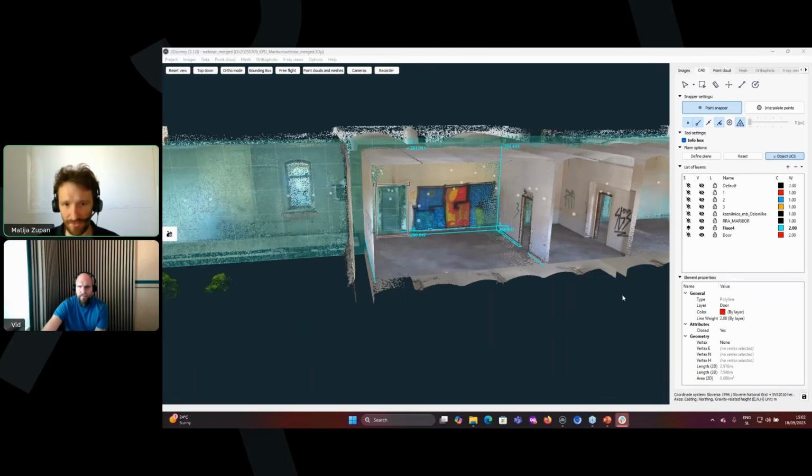So next question is, during the registration between MLS and UAV, have you only used GNSS RTK or have you used any other iterative algorithm? In this one, no, we did not need to, but we did try to use the iterative closest point georeferencing algorithms on other projects we did, in order to say this is the fixed point cloud and move the second point cloud and make it best fit the first one. We did try that before between different SLAM scans. We also tried that between photogrammetry and the laser scanning data.